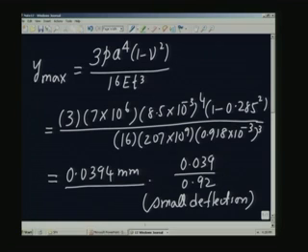And in fact, I can also calculate the natural frequency of this particular gauge, because it becomes necessary to know the frequency at which we can use it. If you are measuring a time varying pressure, you cannot subject this to a pressure which varies very close to its natural frequency, because it will damage the diaphragm completely.